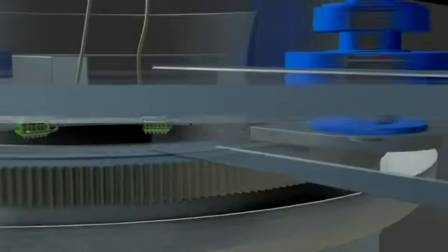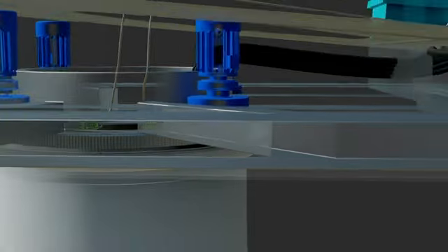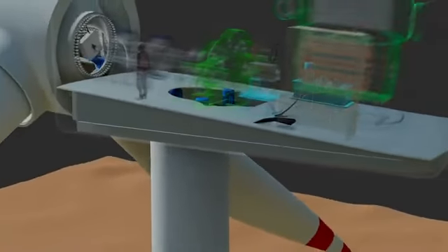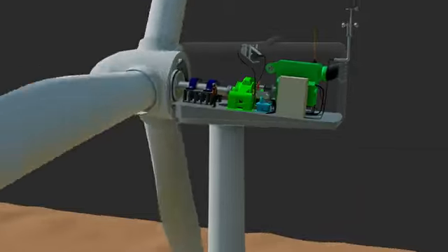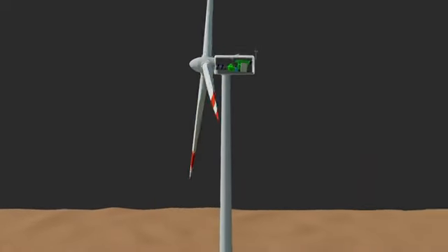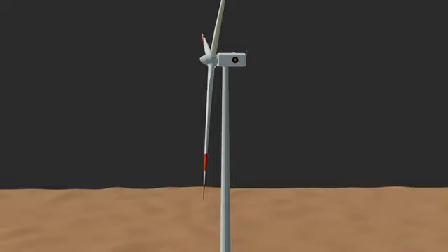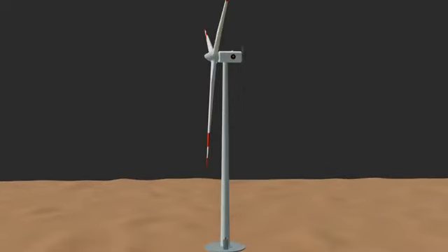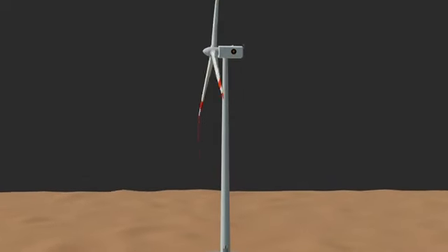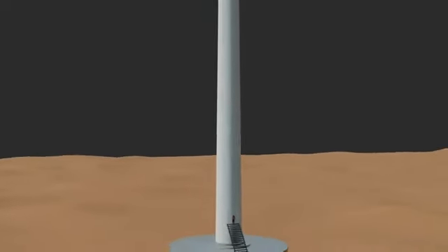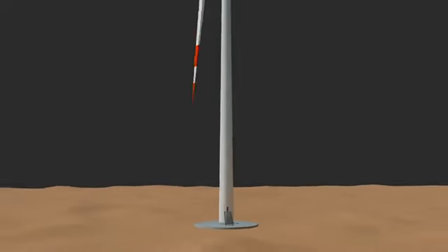When yaw adjustment is complete, hydraulic pressure is released, and springs automatically reapply the brakes, locking the nacelle in position. Towers are designed to support the immense weight of the nacelle and rotor while withstanding enormous wind loads, bending moments, and vibrations. Like the blades, the tower is tapered. Bending moment increases toward the base, so the tower diameter is largest at the bottom and gradually decreases toward the